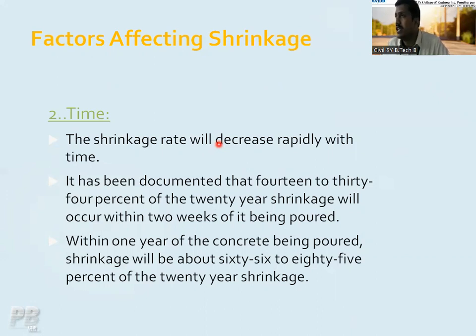Within 1 year of concrete being poured, shrinkage will be about 66 to 85% of the total 20 years' shrinkage.